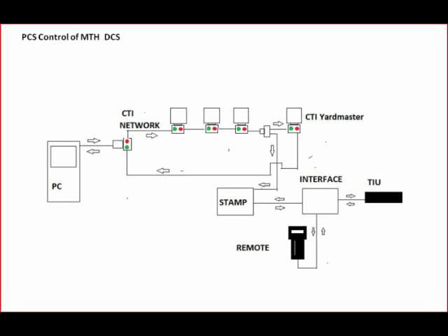It's a more expensive way to go. There's those of you out here that may be familiar with Arduino chips. That may be a less expensive way to go. It requires you to be able to program in C++. If you actually know enough about electronics to make your own little board and power up a PIC, there's PICs out there you can buy for $1.50 that have all the same processing power, but you have to learn to program in either machine language or again C++ and buy the assembly software to do all that.